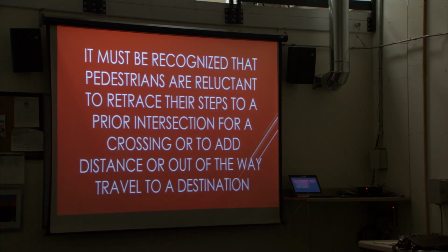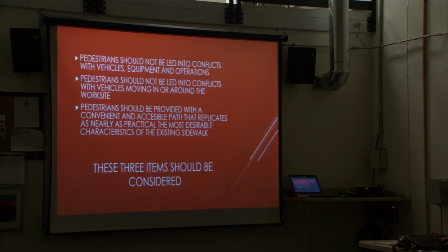It must be recognized that pedestrians are reluctant to retrace their steps to a prior intersection for a crossing or add distance or go out of the way to travel to a destination. So if you've got an open excavation on a sidewalk in the middle of the block, it's much easier just to close that sidewalk at the intersections. Pedestrians should not be led into conflicts with vehicles, equipment, and operations. Pedestrians should not be led into conflicts with vehicles moving in or around the work site.